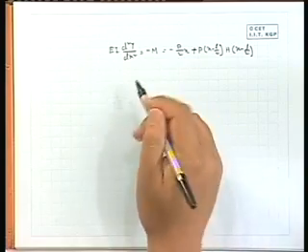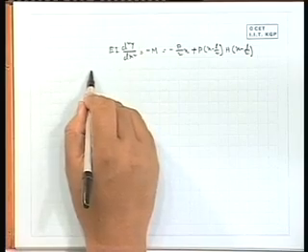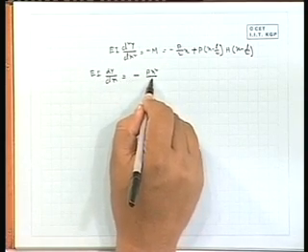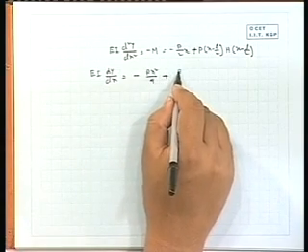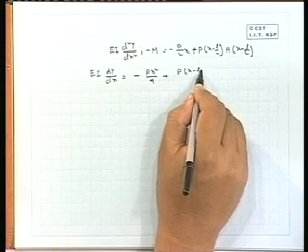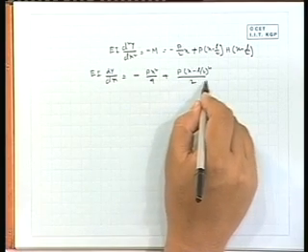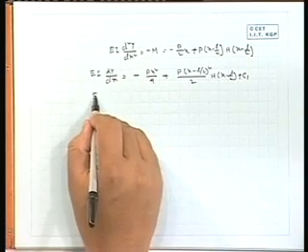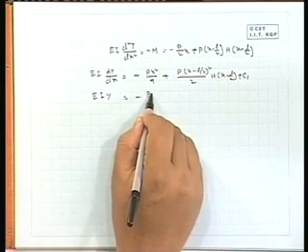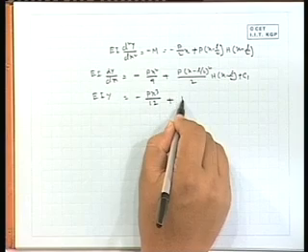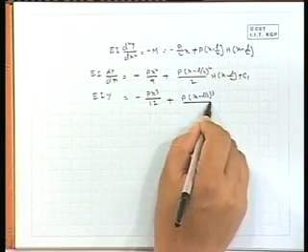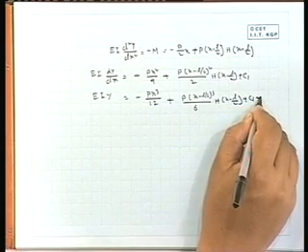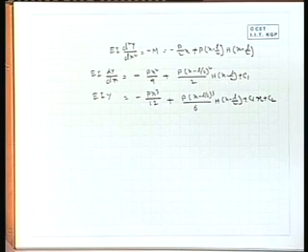Now, if we integrate, in the first step we will get EI dy dx equal to minus P x square by 4 plus P into x minus L by 2 whole square divided by 2 with the unit step function, plus C1. Again integrating, EI y equals minus P x cube divided by 12 plus the cubic term divided by 6, plus C1 x plus C2.